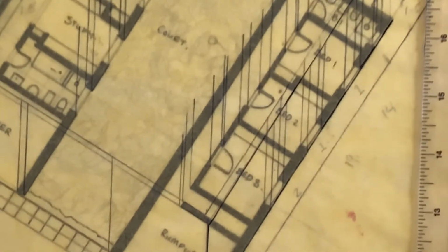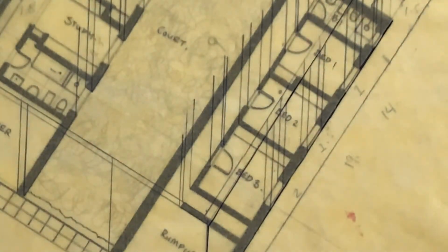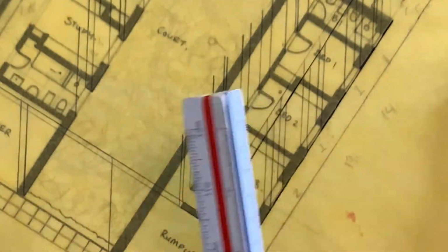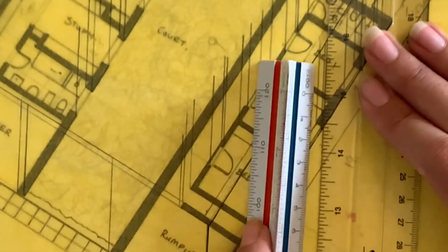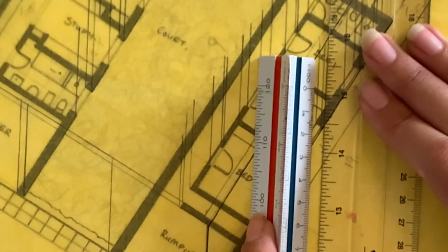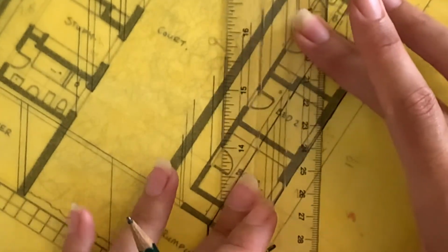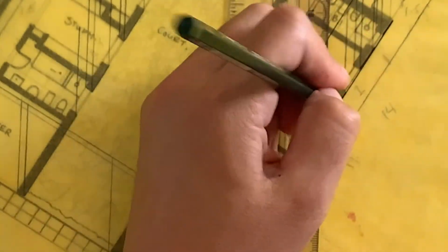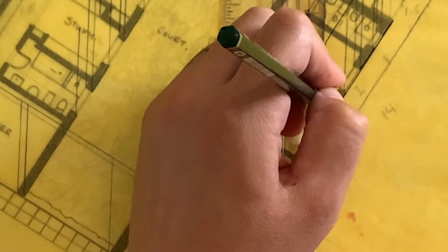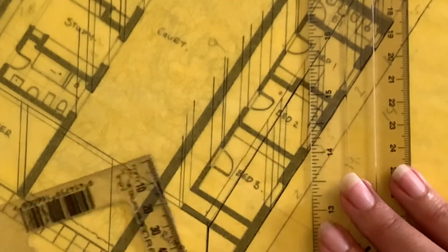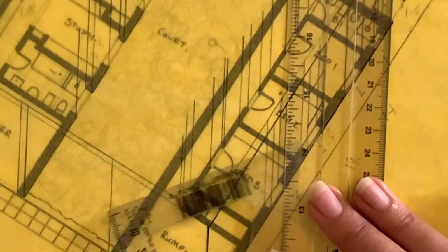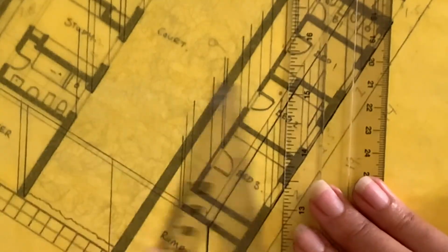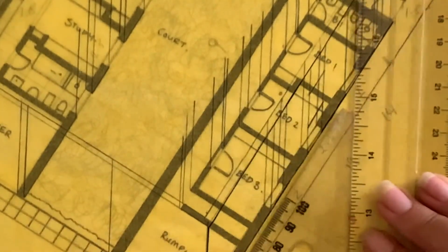Here I'm drawing the vertical lines and projecting the window openings in the external wall plane. With referencing your elevation or section, you will look at the scaled height, and let's just say that our window openings are 1 meter above the floor line. I'll put markers down and then I'll join them. Repeating the same process for the inside of the window as well.